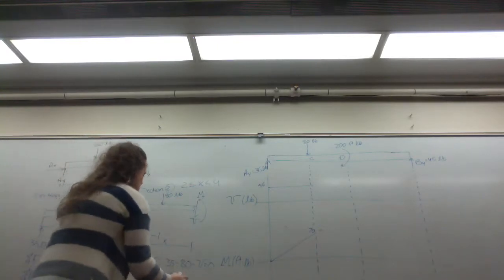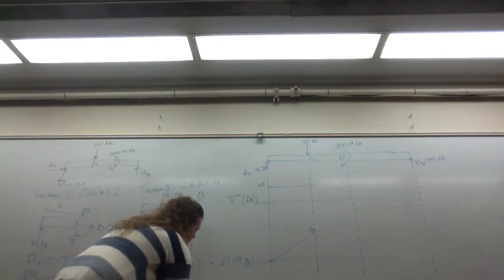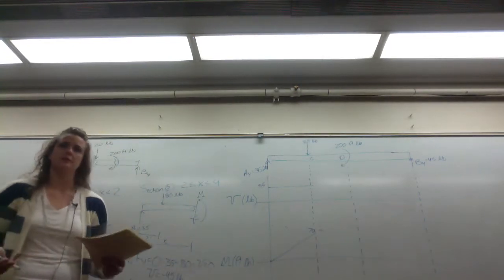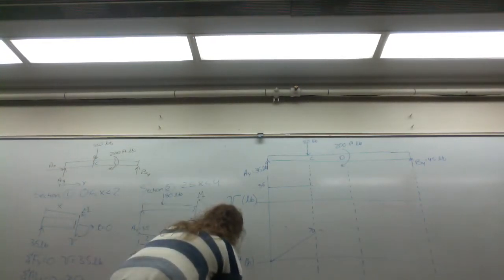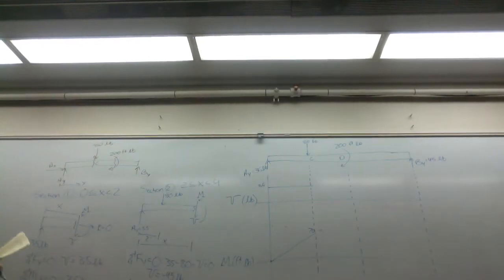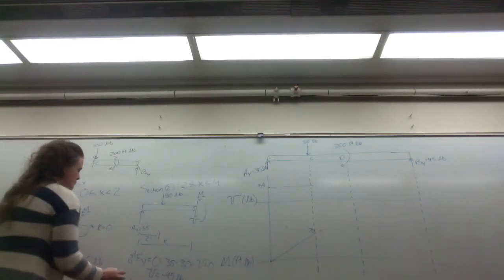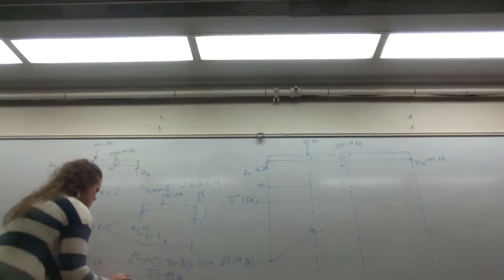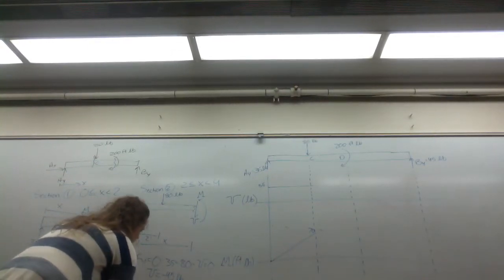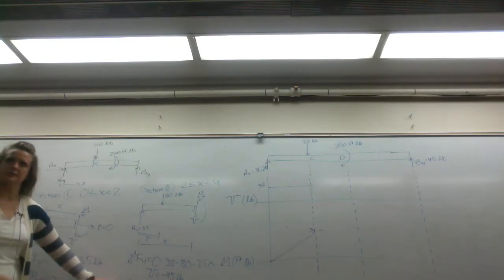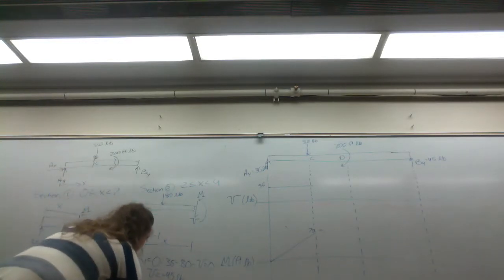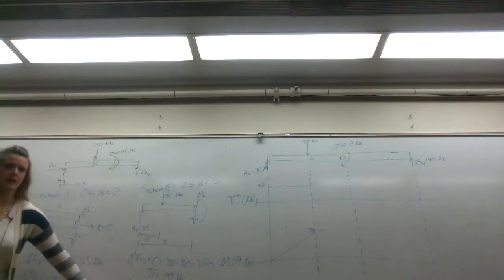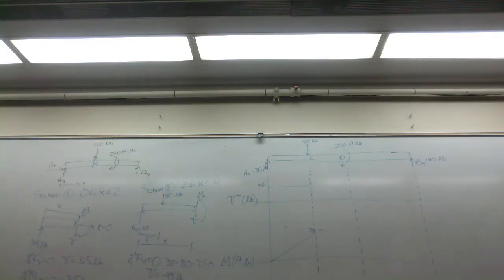Okay? So we have plus 80 times x minus 2 plus your bending moment. Right? So solving for your bending moment, negative 45x. Sorry, guys, I'm starting to act like your physics teacher. Negative 45x plus 160. Okay, that's low. I'm going to write it up here. The moment is negative 45x plus 160.